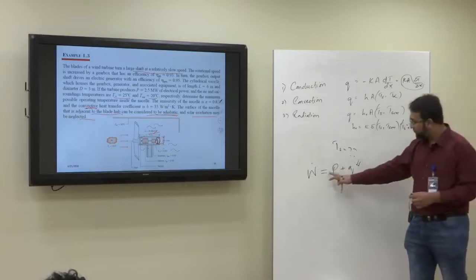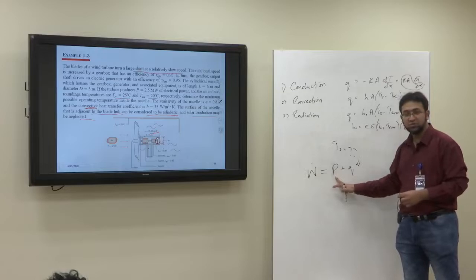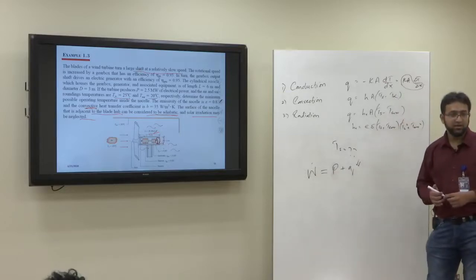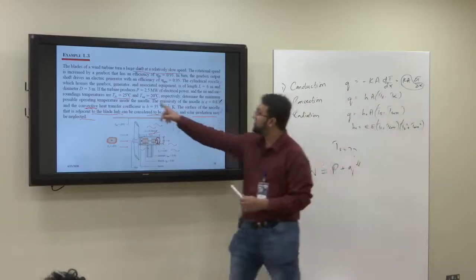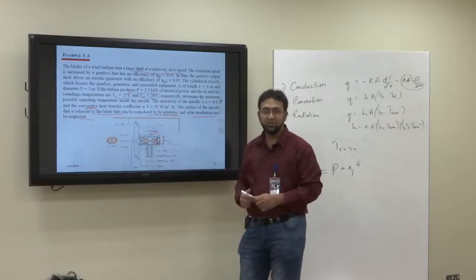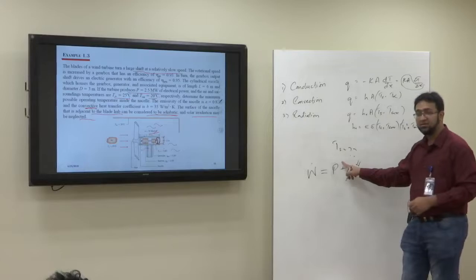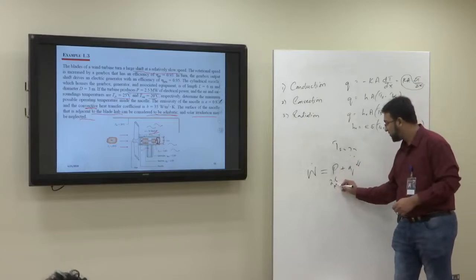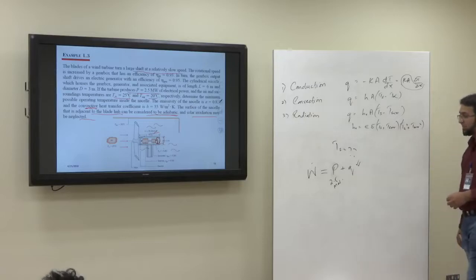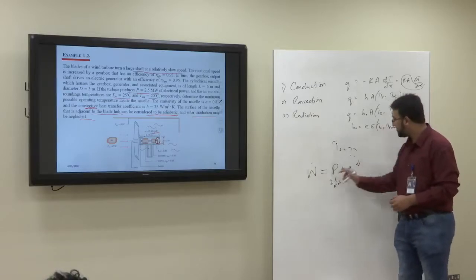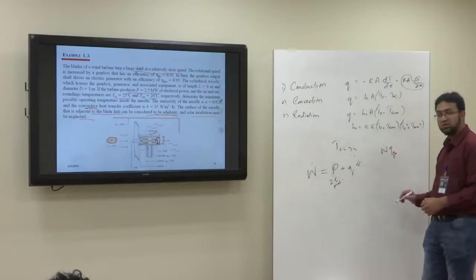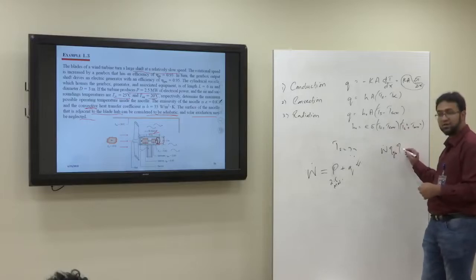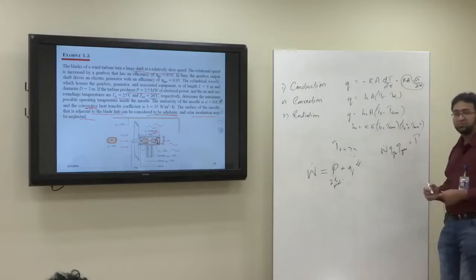Okay. Now, wind energy and the output are related. And what's the relation? You have wind energy, I don't know how much, the input is not given, but it is given that the turbine produces 2.5 megawatt, right? So you know what P is. It is 2.5 megawatt, right? But you know one thing, that whatever the input energy is, when you multiply it with the efficiency of the gearbox and further multiply it with the efficiency of the generator, this will give you the output power, right?